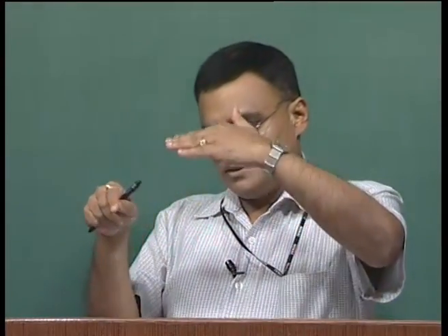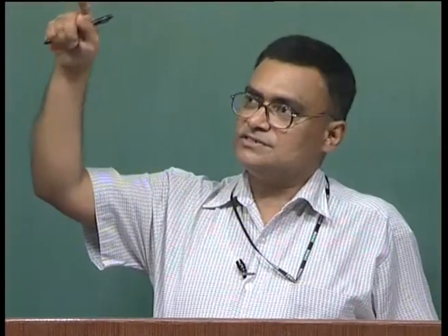Now we are in the stripping section. So we have to now begin with the stripping line equations. So we are trying to substitute xt in terms of y1, total condenser, then y1 x1, x1 to y2, etc., till we have one more equation between xt and xw. Then we make an overall material balance or species balance. We'll have 2 unknowns and 2 equations. So let's continue with our balance with the stripping section.